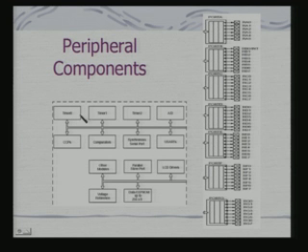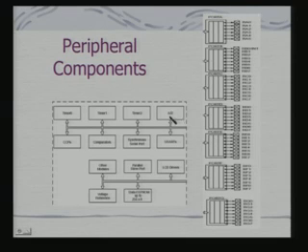There are a number of other timers as well. In fact, I have shown you here the 3 timers. These timers are different from the watchdog timer. The watchdog timer is a special purpose timer. These timers are application specific timers. That means you are expected to program these timers depending on your application requirements. There is an analog to digital converter block to interface or receive analog inputs.